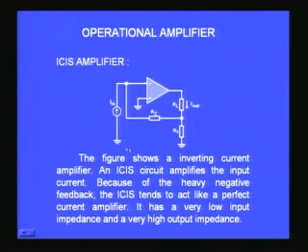the input current. Already I told you, because of the configuration the input resistance is reduced, because along with the input resistance there is another network R2 and R1 coming in parallel. Therefore the effect of parallel resistance is to reduce the input resistance. With reference to output, along with the RO, that RL also is coming, and R1, therefore there is a series resistance coming in series with the output resistance, therefore the output resistance is effectively increased. So that is the effect of the feedback here.